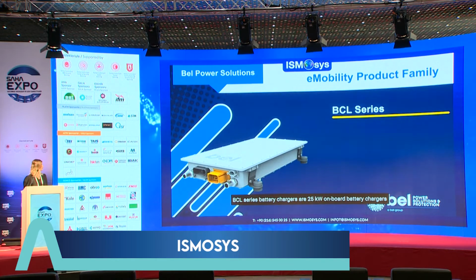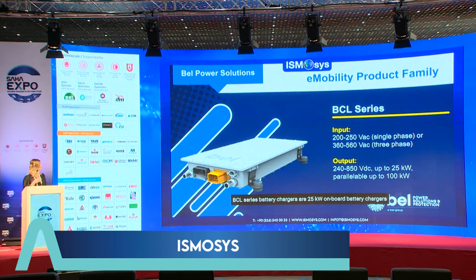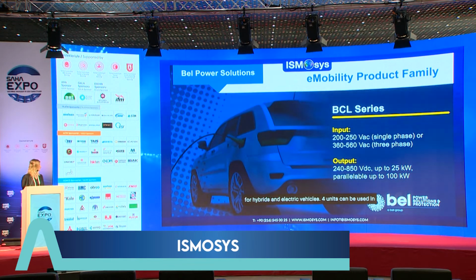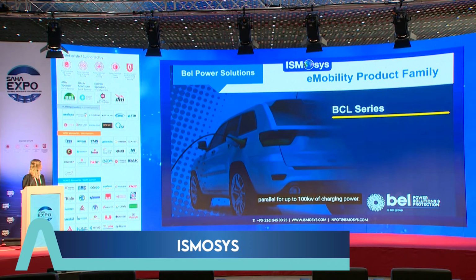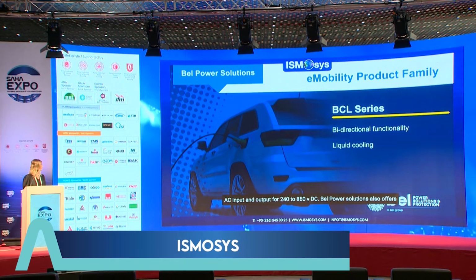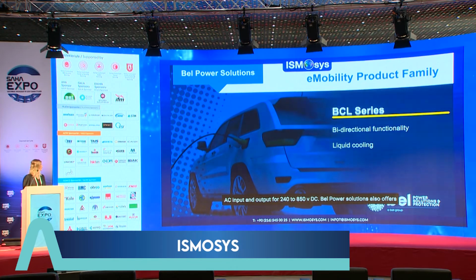BCL series battery chargers are 25 kilowatt on-board battery chargers for hybrids and electric vehicles. 4 units can be used in parallel for up to 100 kilowatts of charging power. They can operate from a single or 3-phase AC input and output from 240 to 850 volts DC.